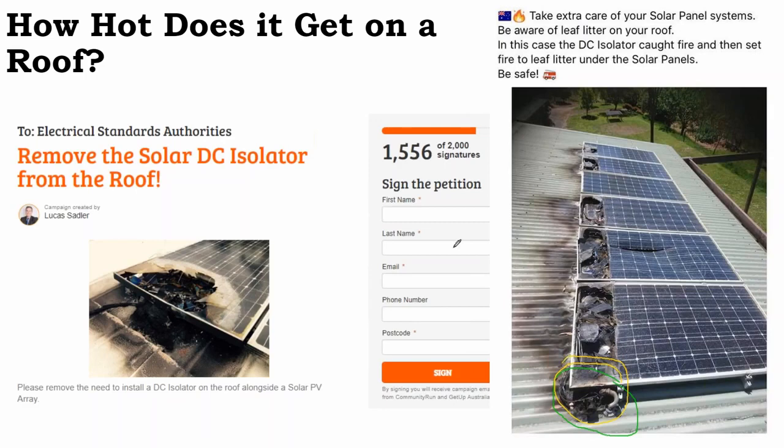The problem with a disconnect switch on a rooftop is not the switch itself, it's the roof. It's a very hot environment. And by cutting that wire inside that disconnect, you're inserting a failure point into the system. And the terminals on those boxes where the cable hits the box is one of the hottest points on the system.